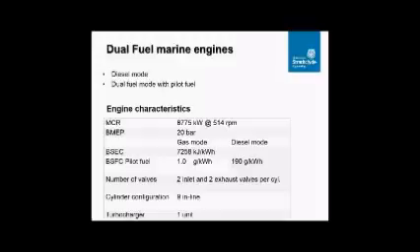In this case study, we will have a dual-fuel marine engine. It can run in diesel mode, where the combustion of the diesel and air mixture takes place in a diesel cycle, or it can run in gas mode, where 99% of the fuel is gas and 1% is diesel, the pilot fuel. It is a premixed combustion. The combustion of the gas and air mixture takes place in an Otto cycle, with ignition being triggered by the injection of the pilot fuel.